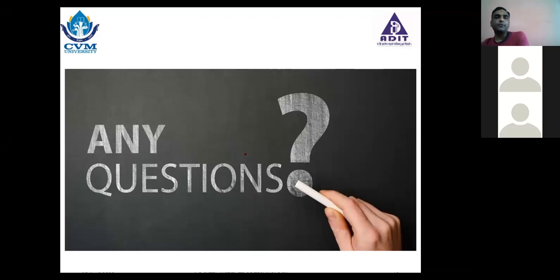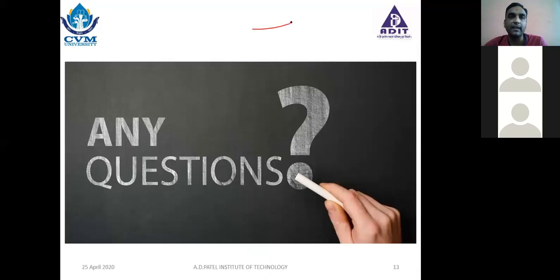Okay, fine. So a question is coming, which is about input impedance. Now what is input impedance? If you take any circuit, whatever the resistance offered on the input side, that is called input impedance. And for amplifiers, input impedance should be high. In short, right now you need to know only that: at the input side, what is the resistance? That is called input impedance. Output side, what is the impedance of it? That is called output impedance. And for an amplifier, input impedance should be high, output impedance should be low. So that is one thing which I needed to clear.